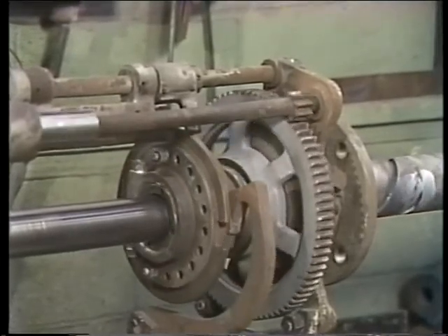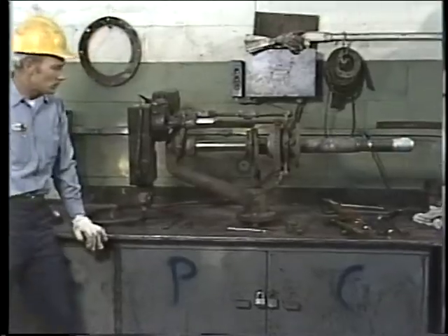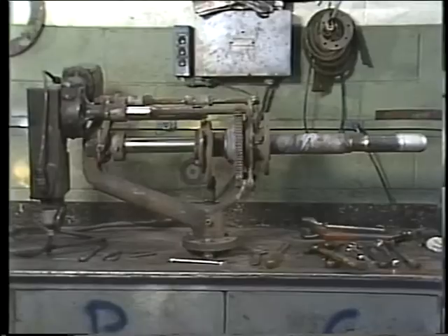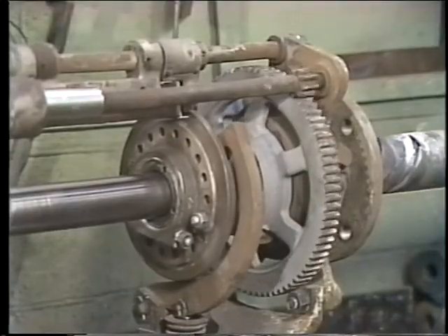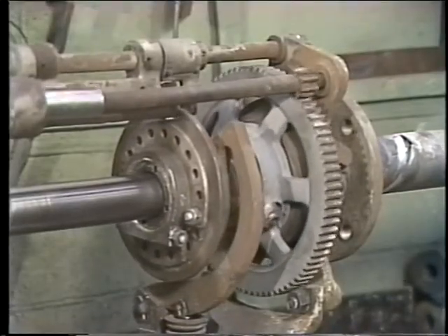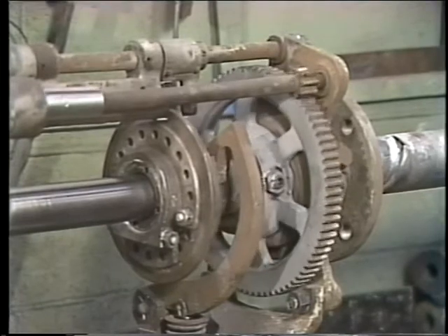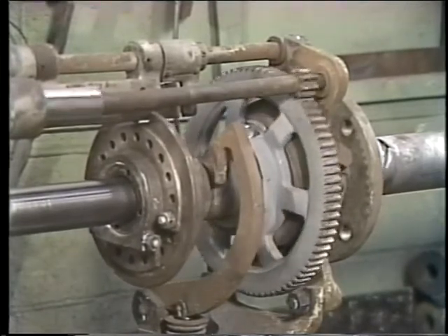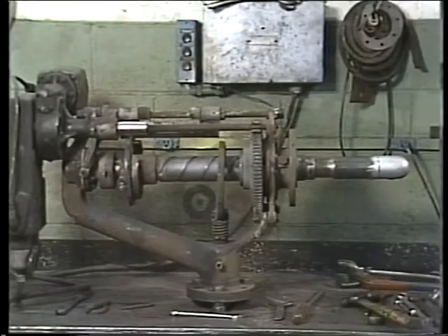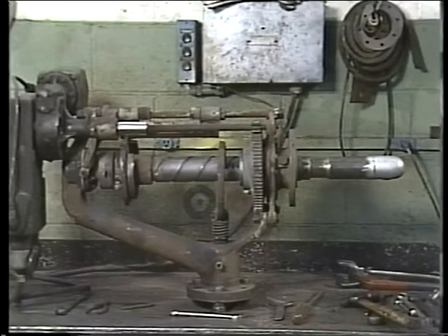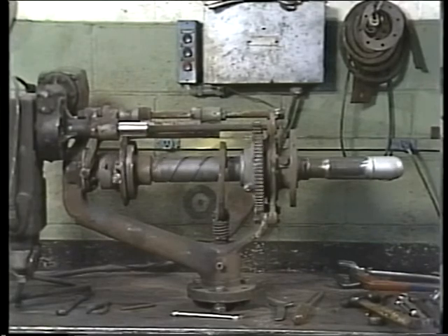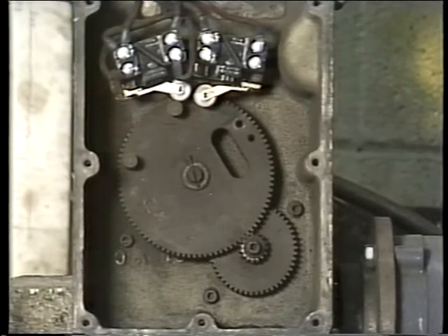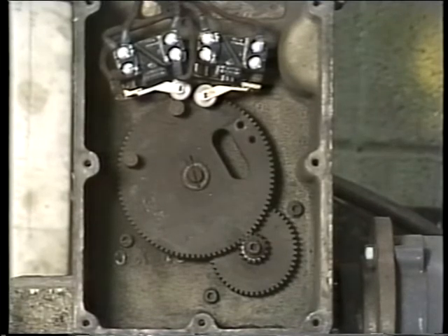After a number of turns, which is determined by the way the limit switches are set, the motor is reversed. When the notch in the cam ring comes around and catches the pawl again, the element stops rotating and is driven back in. The trigger is released by the cam and the valve is closed. At the inward end of its travel, another pawl releases the cam ring so the element is free to turn until the final limit switch shuts off the drive and the element comes to rest.